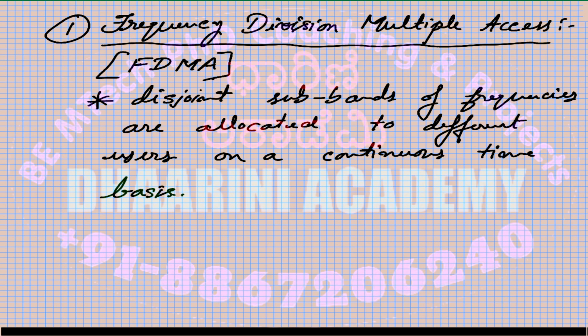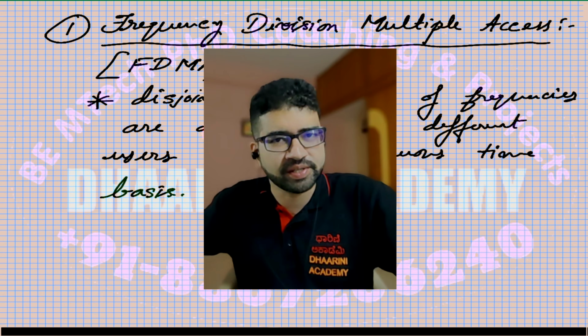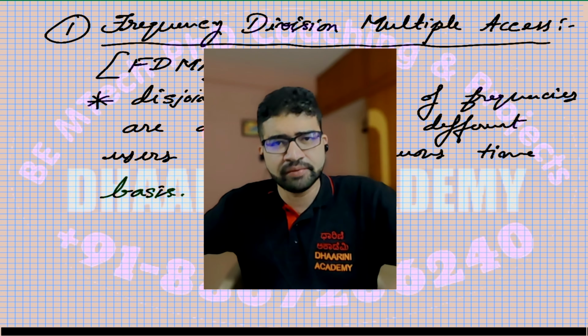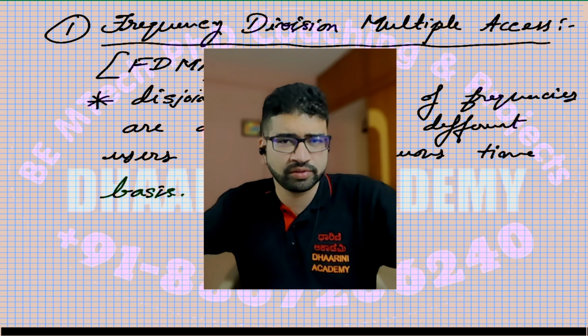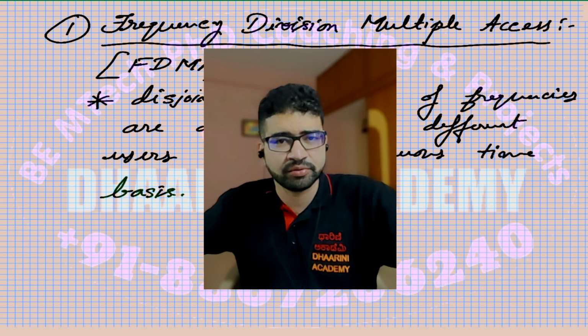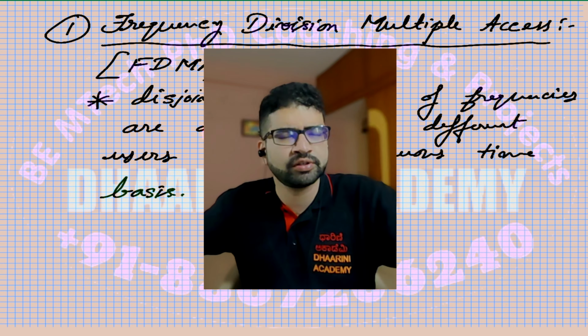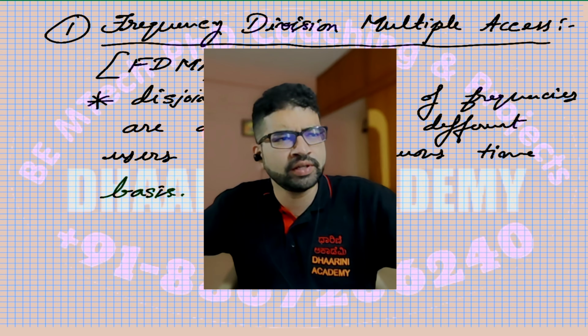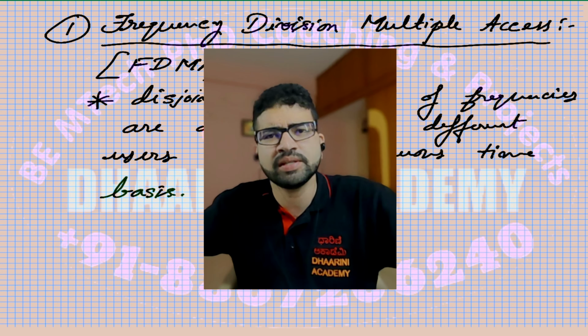So that takes care of what is called the division of the frequency, right? You divide the frequencies into subbands, and each of the bands is allocated for a user. Okay, and within that band, again, you can make multiple users use the subband. But as of now, let's not go to that level. Let's say you divide the whole available frequencies into subbands.